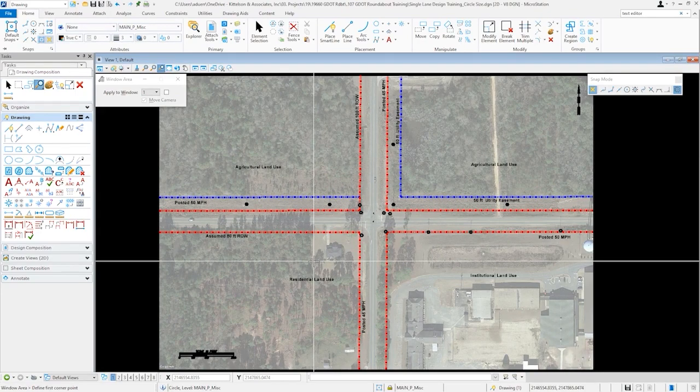Based on previous capacity analyses that were completed earlier, we can assume that this will be a standard single-lane roundabout without right turn bypass lanes. As we discussed earlier in the module during the PowerPoint presentation, Table 3.2 in the GDOT Roundabout Design Guide provides ranges for single-lane roundabout diameters.